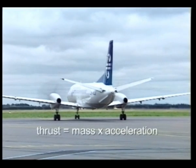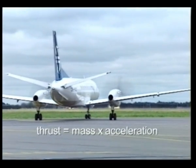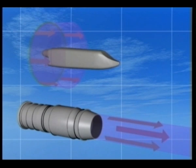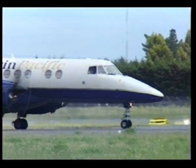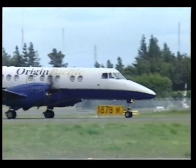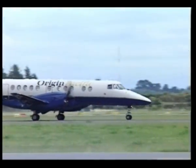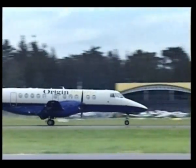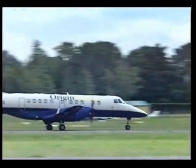Because thrust is equal to mass times acceleration, equal thrust can be obtained from a turbojet engine giving a large acceleration to a small mass of air, or from the propeller of a turboprop giving a small acceleration to a large mass of air. Using mass times acceleration, it can be seen that the thrust experienced by an aircraft depends on the mass of air passing through the propeller disc or jet pipe in unit time, and the rate at which its velocity is changed.